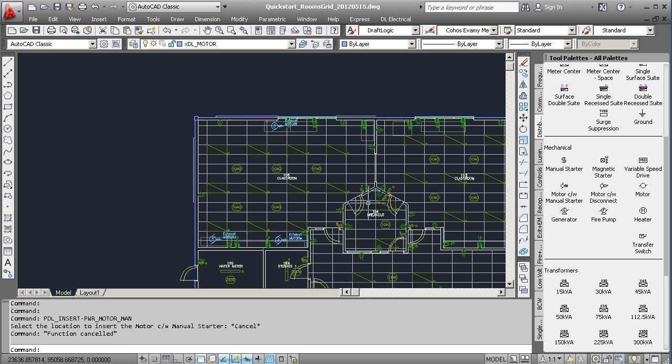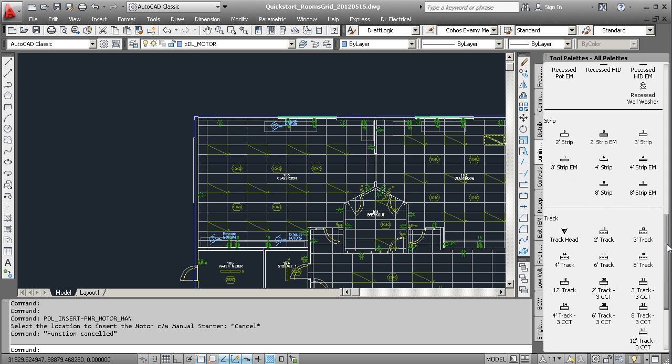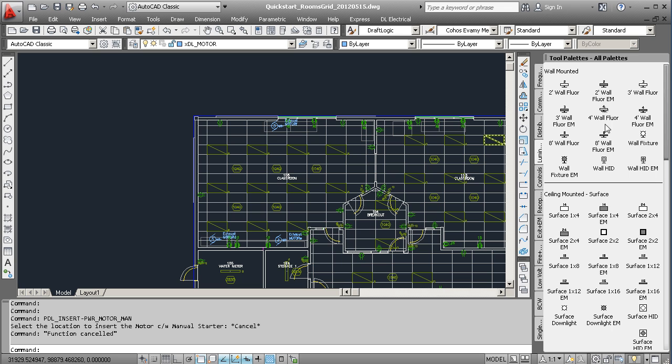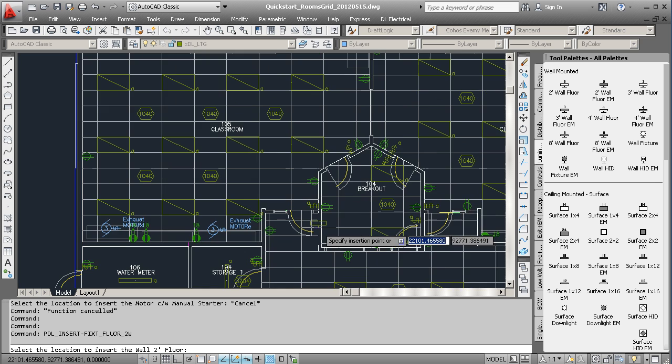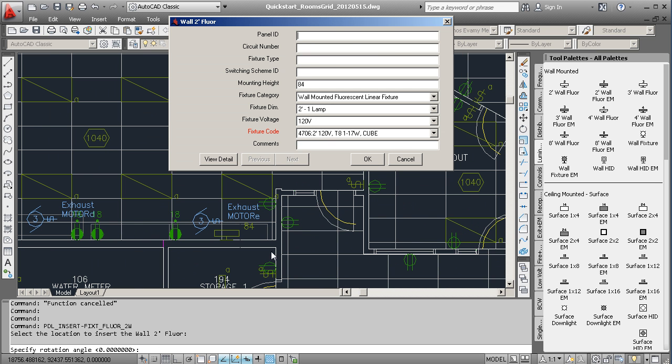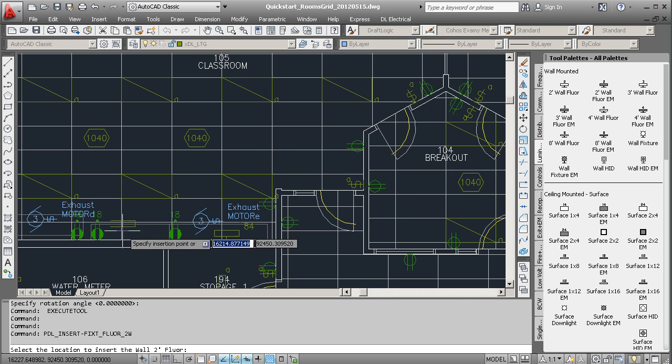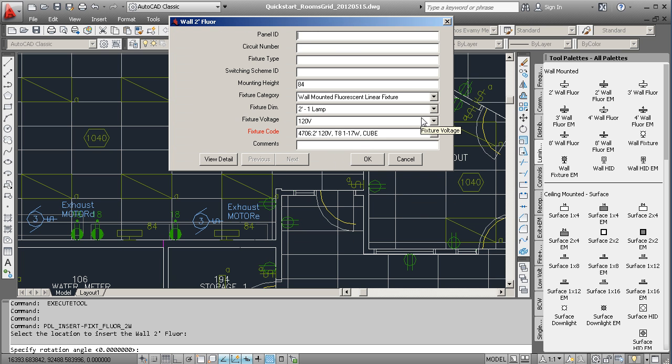So although I did get most of my luminaires placed by automated placement, I can place as many as I want myself. I can remove those automated placement ones. I could skip automated placement. There'll definitely be spaces like perhaps a showroom or executive boardroom where you want a very particular lighting treatment and you'll need to place it yourself. So we have all of the luminaires available for placing on your own. But of course I want to stick to my 277 volt lighting pattern.